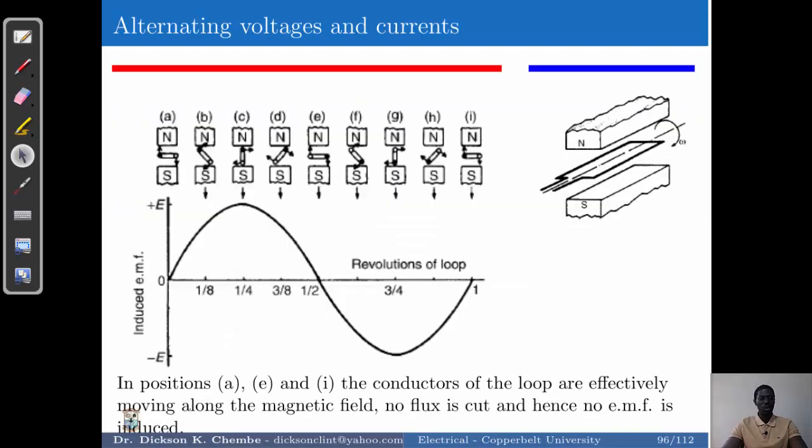In this example, we take one coil and insert it in between two magnetic poles. From the poles, the magnetic field is going to flow from the north to the south, like so. The magnetic flux is going to be concentrated on this area, so there's going to be a higher magnetic flux density, which ensures that the coil can produce enough induced current.